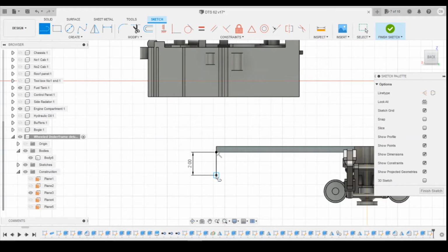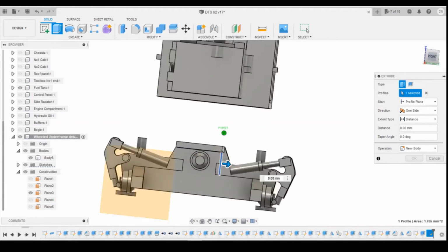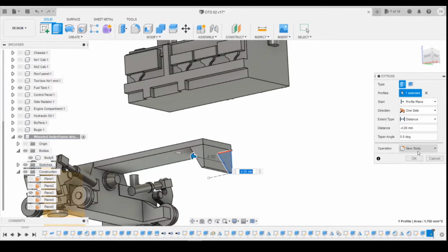I'm going to then create just a little bit on the bottom. Now on the real thing it looks pretty much diagonally straight up. I'm just going to create maybe 0.3 on the bottom, just as a little bit of wall thickness there when it prints. And then I'm going to diagonally come up 60 degrees. Delete that number there, bring that down to 1. Escape that. That's right. So I'm going to snap it up there like that, and then extrude from there to that side. Tell that to join.